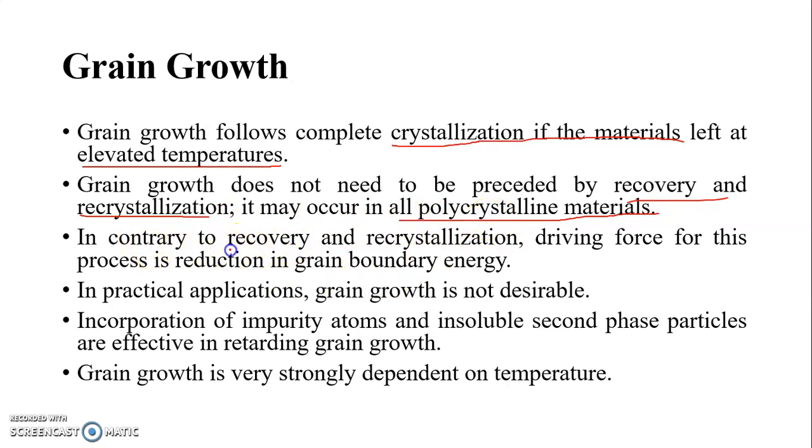In contrast to recovery and recrystallization, the driving force for this process is the reduction in grain boundary energy. In practical application, grain growth is not desirable because it loses the strength of the material.